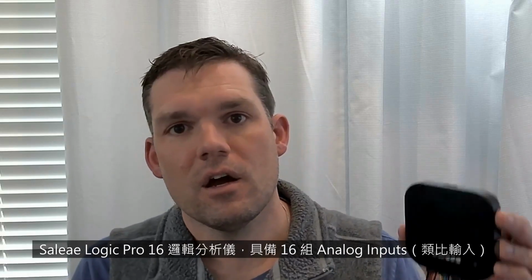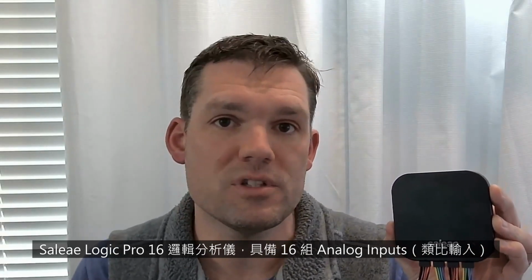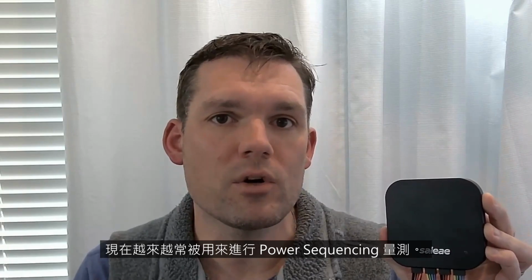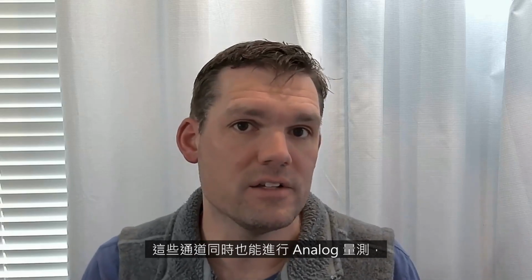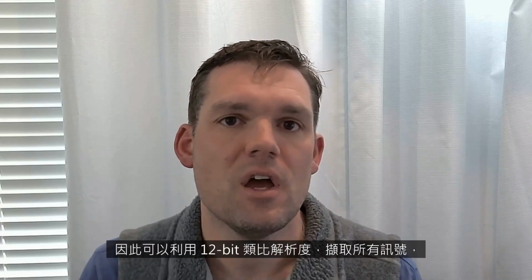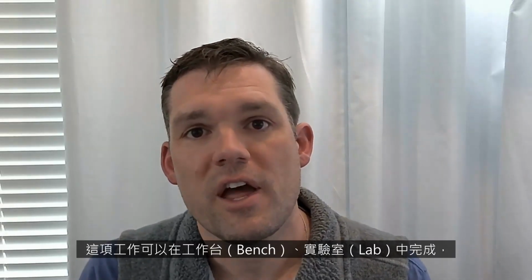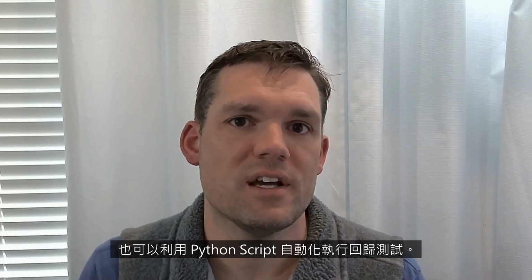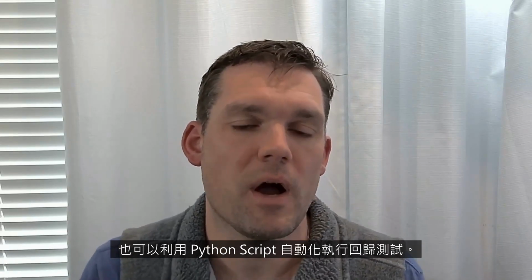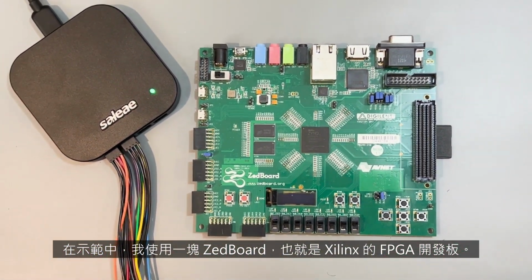At Saleae, we're finding that our Logic Pro 16 logic analyzer, which has 16 analog inputs, is increasingly used for power sequencing measurements as well. So users will hook up all of the digital lines, which also are analog lines, so taking 12-bit analog measurements of those lines, and then capture that data in our Logic 2 software. That can be done both at the bench or in the lab, or as regression testing that is done automatically using Python scripting. For demo purposes, I chose the ZedBoard, an FPGA board from Zynq.